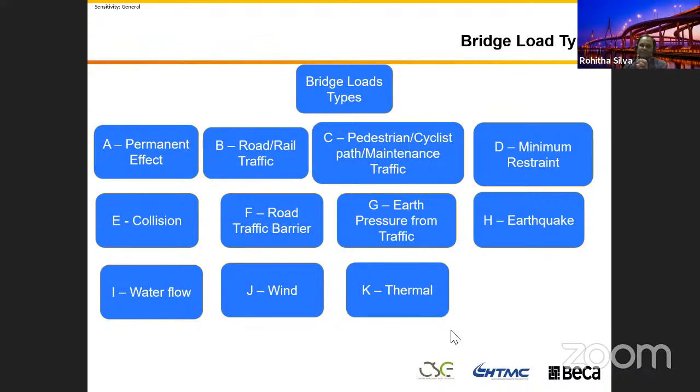Because of that, in bridge design you have to be really mindful when you are combining loads. The reason I asked you to use the permutation and the load combination, plus, minus, all sort of thing, is that you can develop a few thousand load cases.